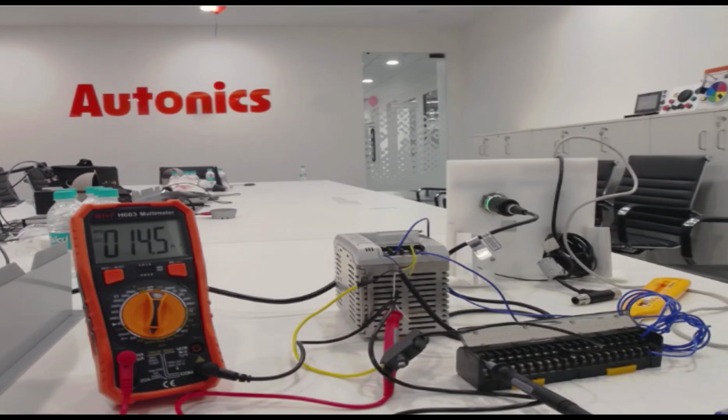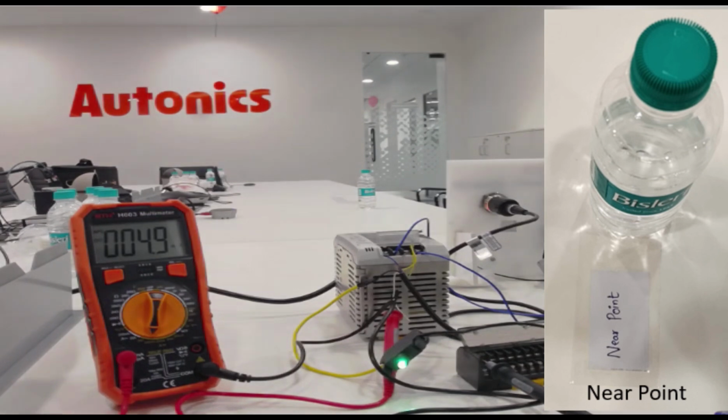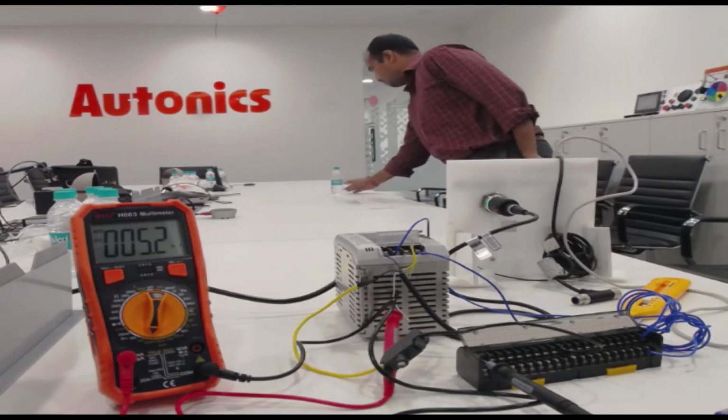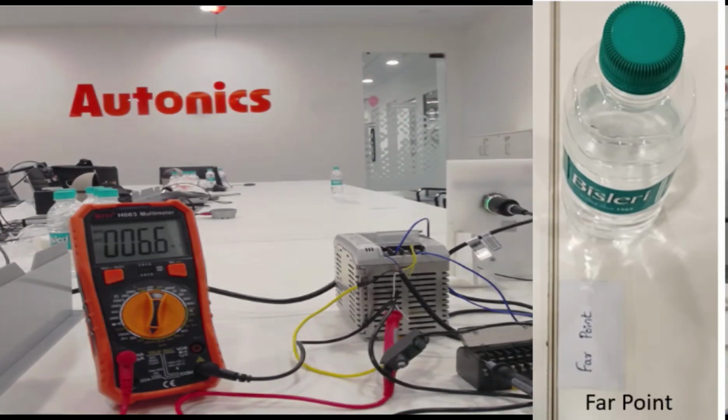I have already fixed on the table a near point and a far point, and using those, let us start and teach the analog output with respect to that near and far point. So this is the near point, and right now at the near point, it is giving me 4.9 milliamps. And this is the far point. At far point, it is giving me around 6.6 milliamps.